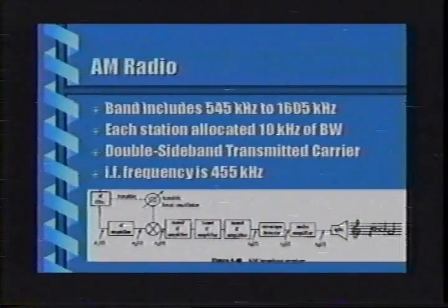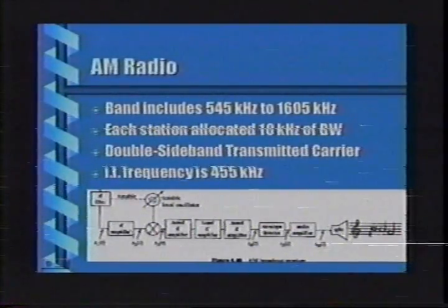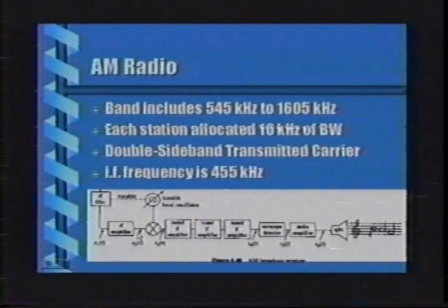And I show here a block diagram of an AM receiver. I know it's a little hard to see the details here, but I just want to talk about the overall operation. The signal comes from the antenna, goes through a tunable RF filter. It's tunable because you have to reject the image station. The process that's used to shift the frequencies into the passband of the IF filters creates a second frequency known as an image. We then typically have some RF amplification, radio frequency.